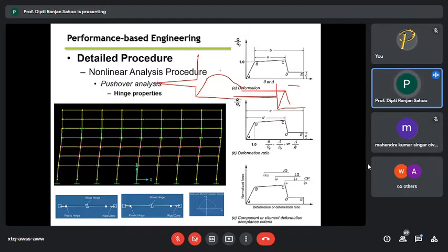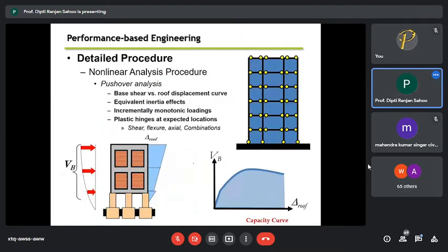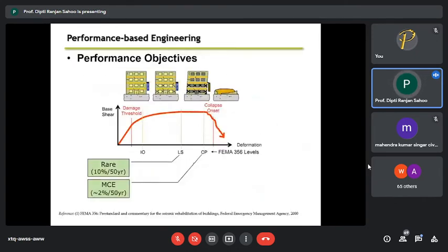So this is a flexural failure, this is the shear failure, and I don't know how any of these members will fail. I have to define this shear behavior and the flexural behavior along with their interaction in my program. To do this, FEMA 356 is one of the best standards. FEMA 356, somewhere I have mentioned. Yeah, you can see here.